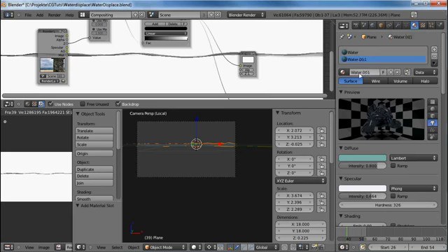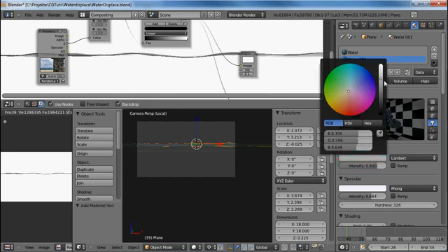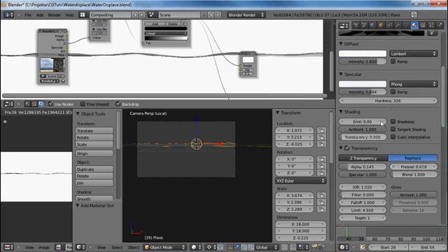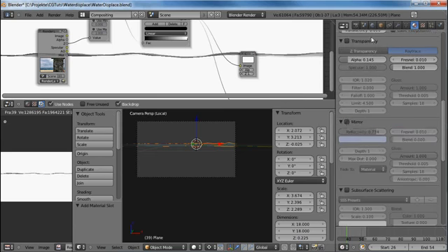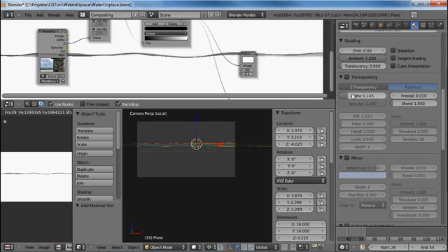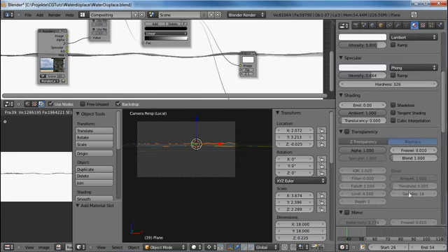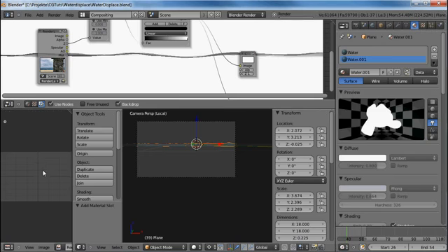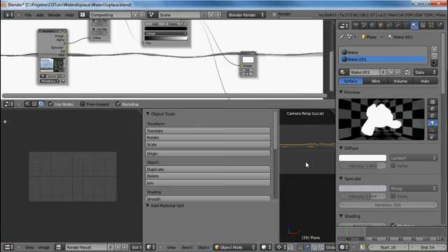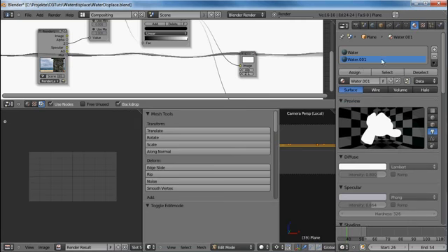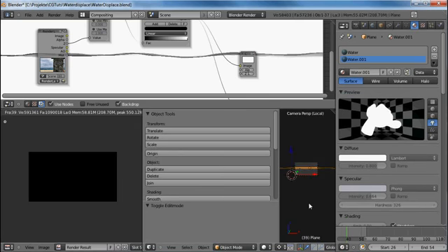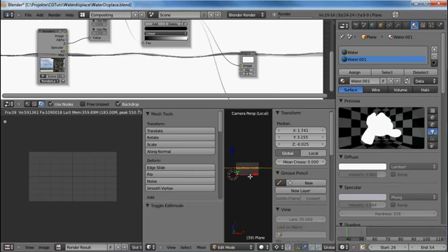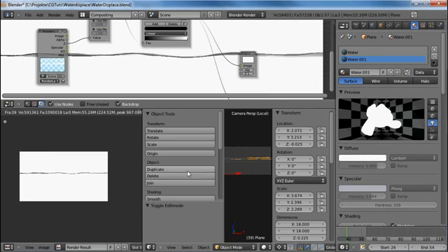So I'll create a new material and make this white. It needs to be white or black, but nothing in between. No transparency, no mirror, just transparency up, and make this shadeless. So this way we'll have a shadeless water surface. Of course, you have to assign the material to the entire water surface. To do that, just tap into edit mode, make sure everything's selected and press assign.